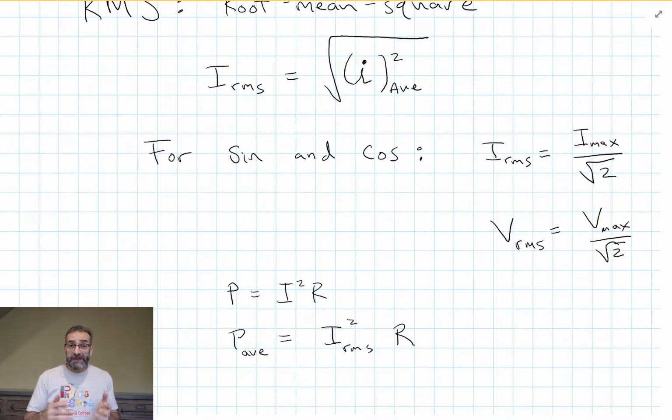A digital multimeter just reports a single number, right? A digital number in the display when you measure a voltage or a current. So if you're measuring a voltage that's constantly changing in time, you'd have a hard time with that. The number would always be changing. But if you change your multimeter from DC to AC, it will report the RMS value.